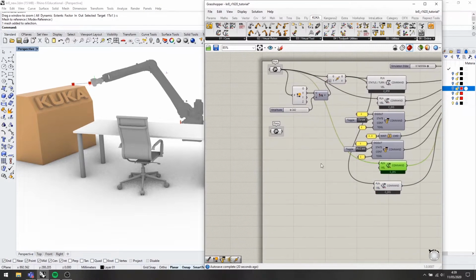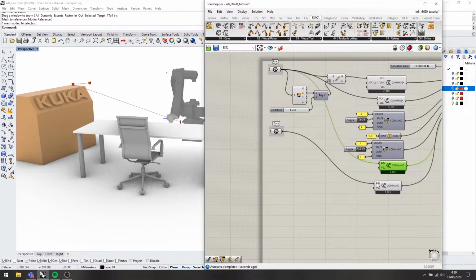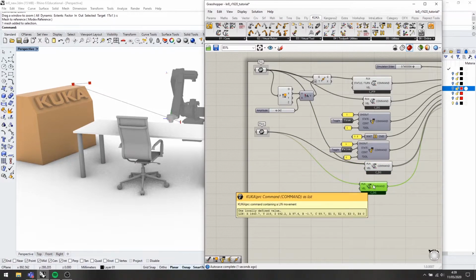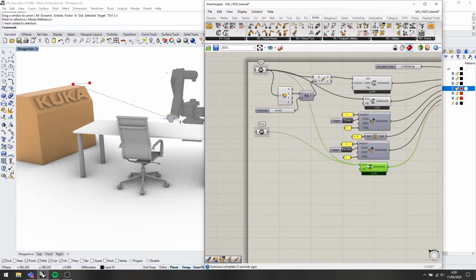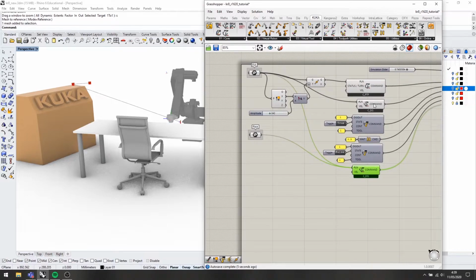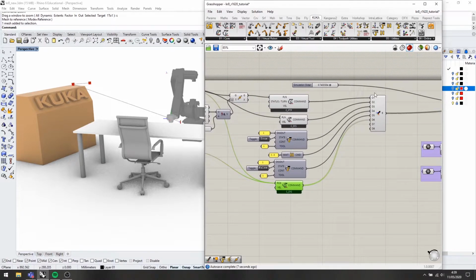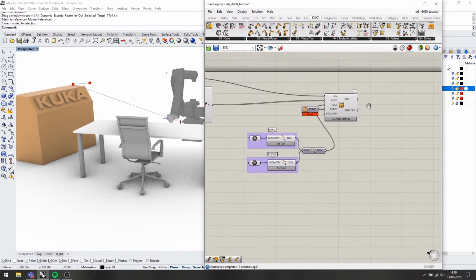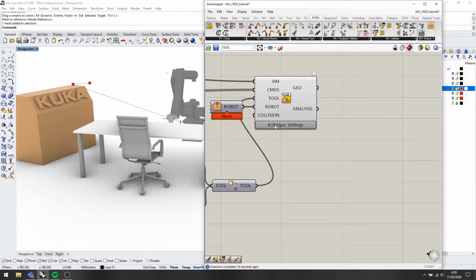What have I got to? I've used the wrong component. So then linear here, which we can put in there and get rid of that. So we can recycle components when they're in order, because how this happens is how it's going to be interpreted by our analysis. If we want to have a quick look, we can click on KUKAprc settings.